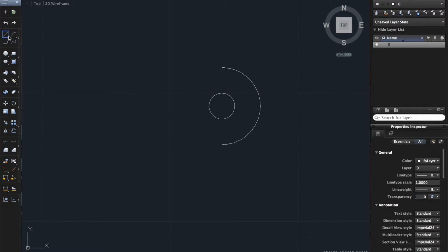So we are going to take our line again, now that we have this half circle. We want to keep this half circle because that's our mounting point, right? So we'll go this way, and we're going to do 1.5, bam, and it's going to give us our line. Now if we wanted to, we could go straight across immediately to have a flat mounting point and just complete it. But we're not going to do that. What we're going to do is 1.25, 1.5, and we're just going to hit escape.